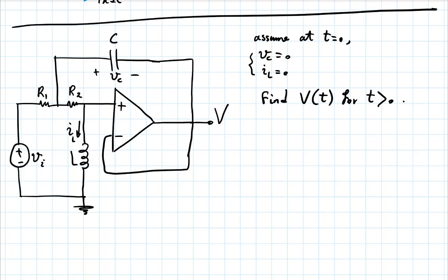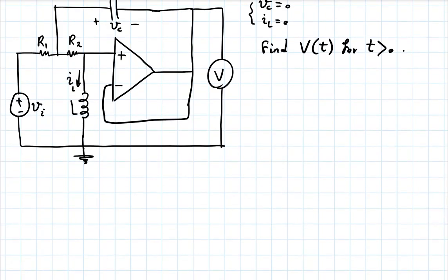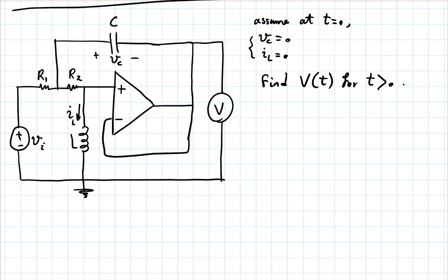No difference. Okay, so that's good. The voltmeter has infinite resistance, ideal voltmeter, so it's not drawing any current there. It's just measuring that voltage difference. It's the same problem. Okay, what can we say then? Let's see if we can simplify things on the circuit before starting to write equations. So this is my ground, and here I have VI at this node. This is all one node, as you guys identified.